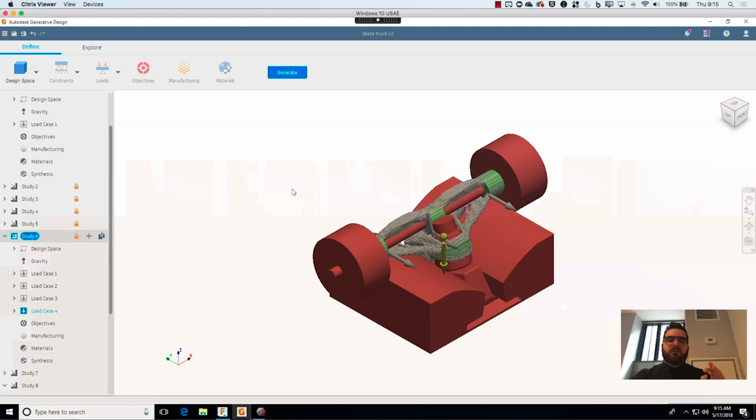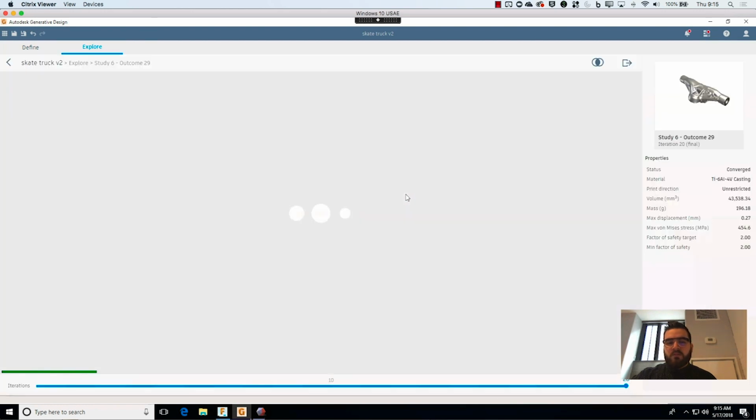I use that lattice as a starting shape. What a starting shape does is essentially tell it that you want to start with this and then run the generative process again. It's basically going to take that as your starting point rather than trying to connect everything together on its own and then run the algorithm again. If it does it that way, you end up with essentially just a feedback loop. So in my case, I ran that, and that's how I ended up with this.